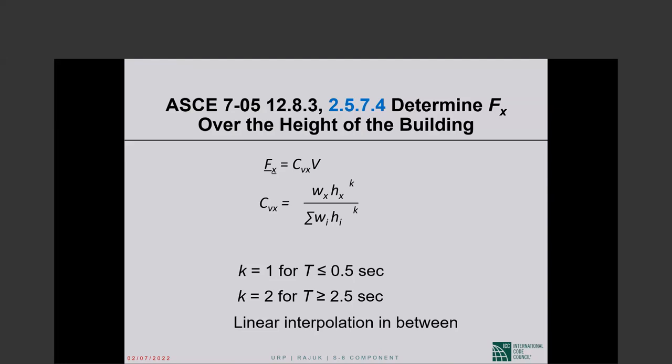That way, if you take that option, you are dumping more of the lateral load towards the top of the structure, thereby getting larger overturning moment for the same base shear, which is essentially penalizing your client for no reason at all.